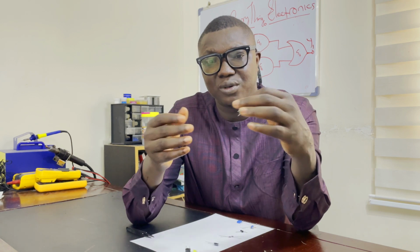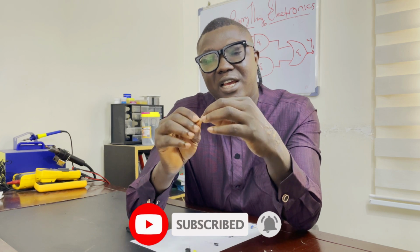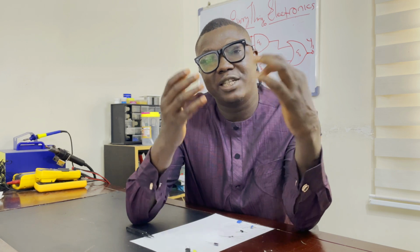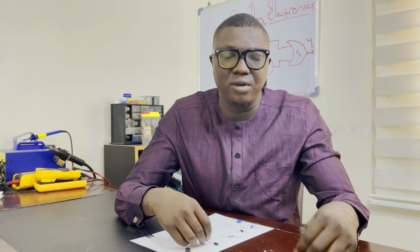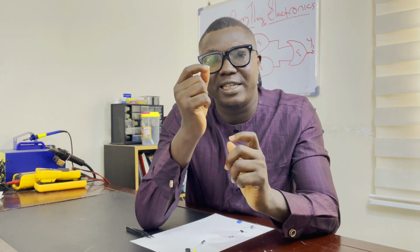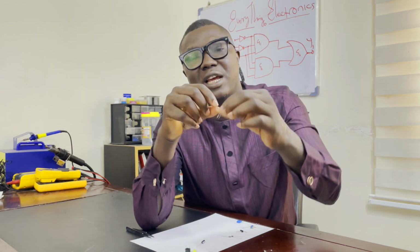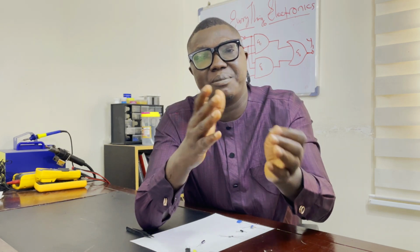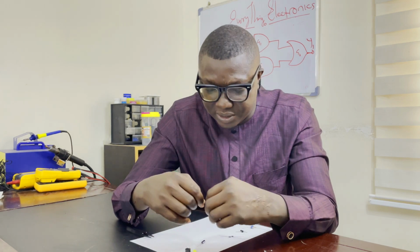It has so many applications in electronic circuits, and we have polarized and non-polarized. The one I'm holding is a polarized capacitor, which means it has a positive and negative. While we have a non-polarized capacitor like this, which is called a ceramic capacitor. It doesn't have a polarity, so you can put it in the circuit without minding the polarity. It doesn't have negative or positive. That's what it means by non-polarized capacitor.